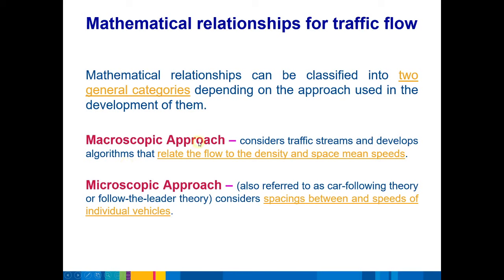But if we want to know broad things, like how many vehicles are able to move across Ballarat, or how many vehicles are able to move through the Melbourne CBD, and where the choke points in the Melbourne CBD are, then we would use a macroscopic approach. To use an analogy to fluid mechanics, a macroscopic approach is kind of like looking at a whole series of pipes in a water main distribution network. We want to move water around the network, and the water can take as many different paths as it wants to get to its end goal. Whereas the microscopic approach is looking at an individual T-section bend. We're trying to calculate how much water is going left and right based on the pressure on either end.